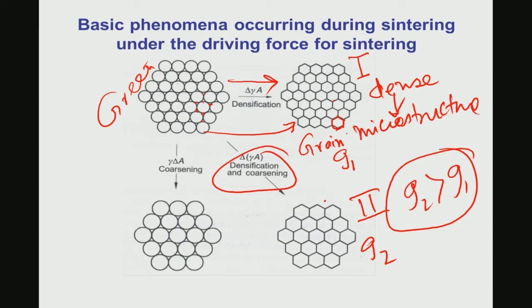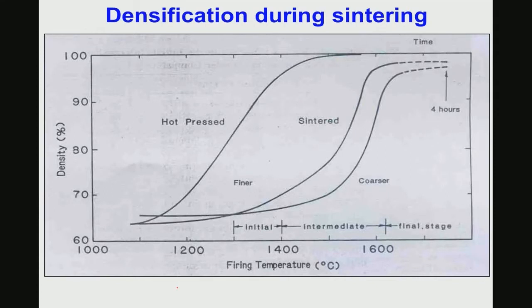So, inappropriate selection of the sintering conditions can lead to grain coarsening. Third scenario is that if you have a very poor understanding of the overall sintering process, then you arbitrarily select the temperature of the sintering, then the particle size will simply undergo coarsening and increase, but there will be no grain structure formation. So, this is also another important thing in the sintering process.